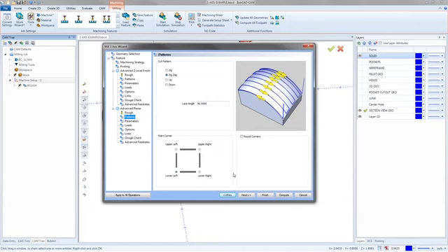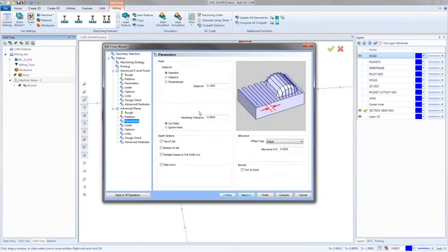So a wall, let's say a wall parallel to the direction you're cutting in. Because it's just like if you were walking along a cliff and you walked back and forth and slowly stepped over every time you got to the end of the cliff, you took one step closer to the edge, and then you walk back, and then you step closer to the edge. Eventually, you're going to fall off the cliff. Same thing happens with the planar toolpath, and you'll see those kind of results right over here in these areas. It's not going to be a good finish right here.